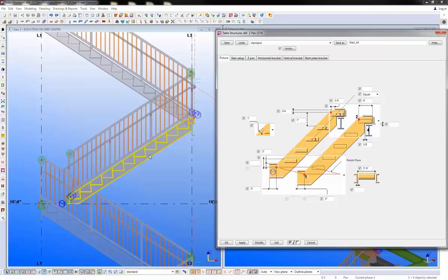So I'm going to go ahead and adjust some properties before I delete it, now that I've got this dialog box open. I'm going to go ahead and change that again to be extending out. I don't know what these dimensions are going to be just yet. I do already have this stair laid out, but I want to show you, just in case you don't have it laid out yet, kind of a poor man's way to check and adjust as required to get the proper rise and run for your treads. So I'm going to leave that as a foot for now.